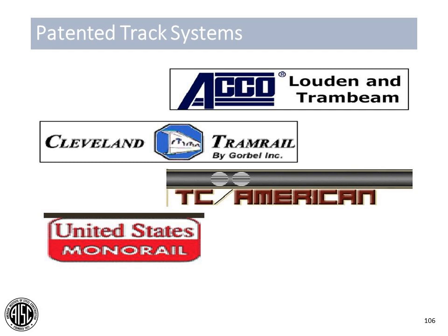We had a question on patented track systems. Are runway beams designed by the manufacturer when you use a patented track? Yes. Typically, you would specify the criteria for the design, or it may be that the process equipment that's driving this design will actually specify what track system is needed. But typically, yes, these suppliers will actually design their track system. We, as the engineer of record, would just need to specify the design criteria that they would need to incorporate in their design. Okay, thank you.